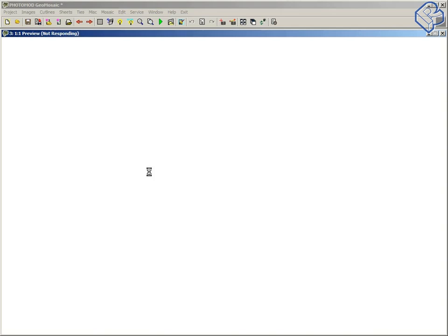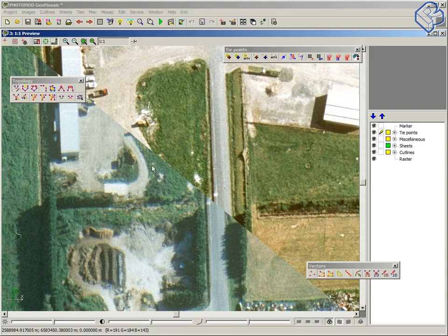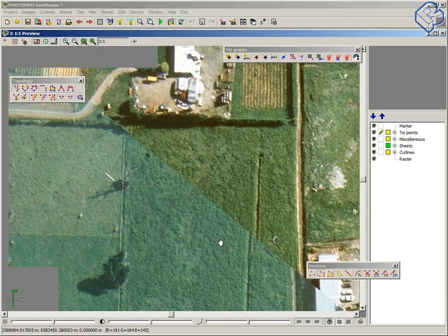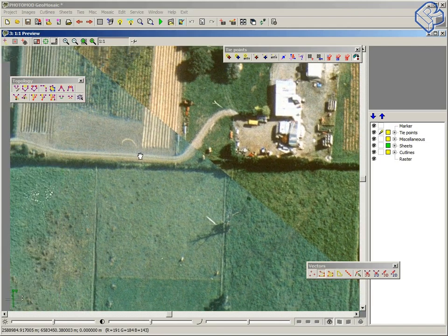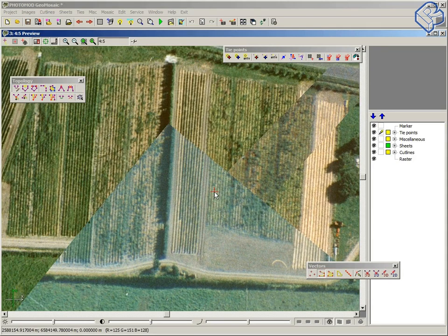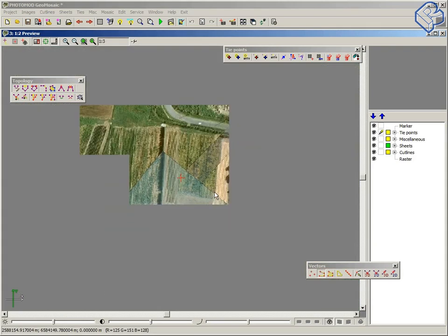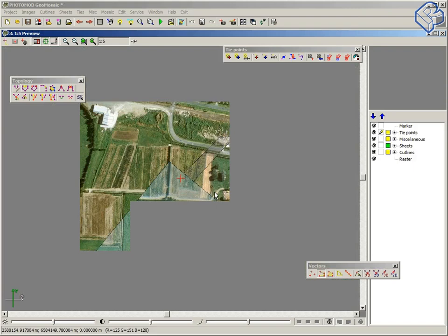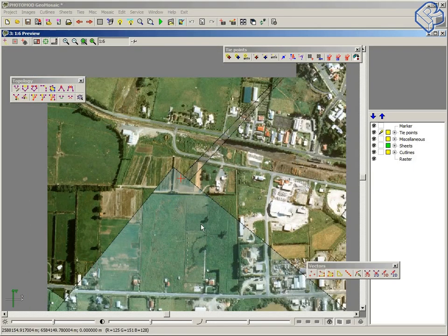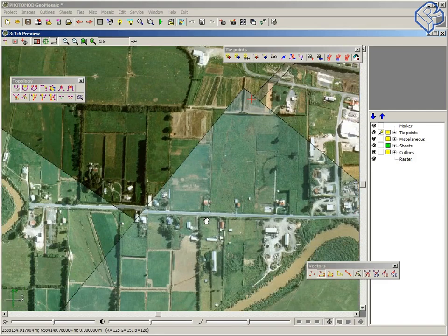The first one depends on the accuracy of georeference of these images, or it may be the influence of relief, because these images have been rectified without it, as I have already said, and so we have some gaps along the cut lines.